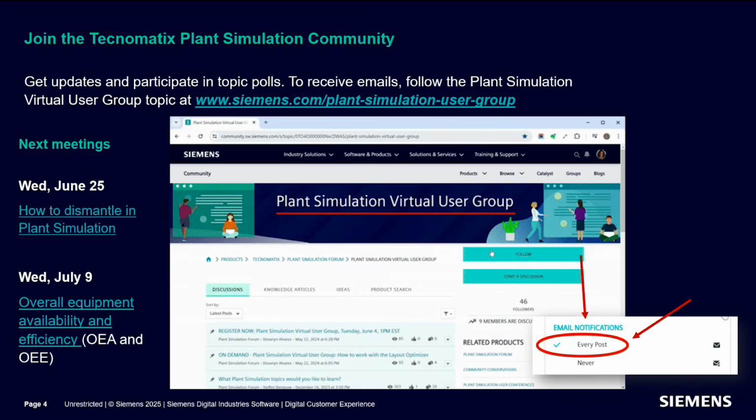But you need to check it in each version of Plant Simulation. In version 2504, you can already define a sequence of assemblies and the assembly list itself, but you cannot change the service in between, so you need to set several services at the same station. But you can find a webinar on this topic. We had already covered it.